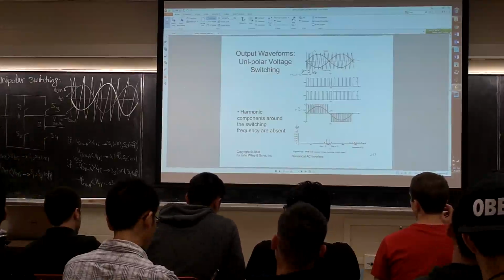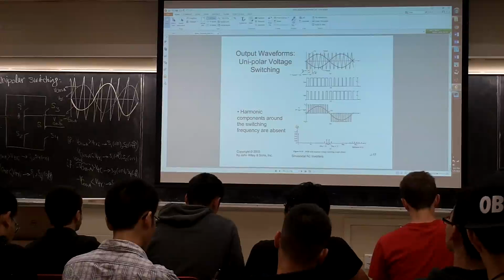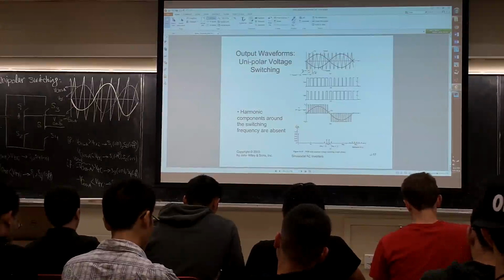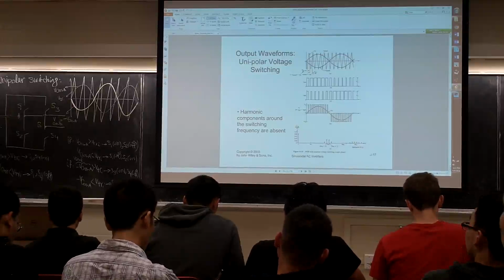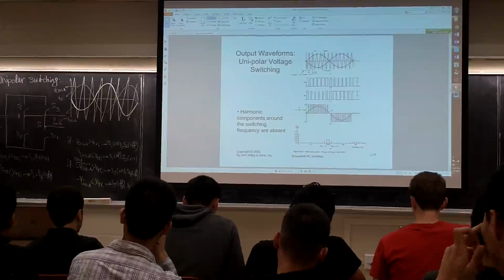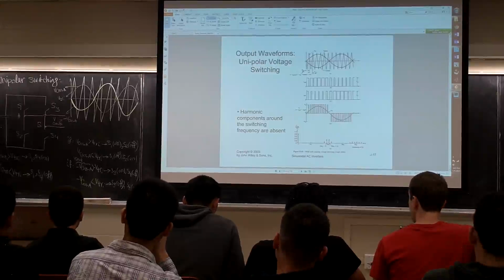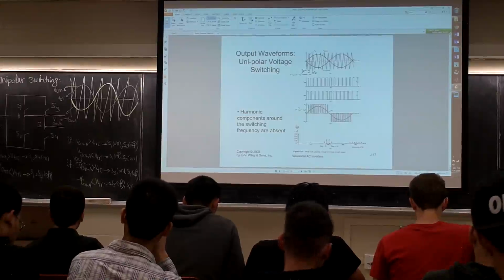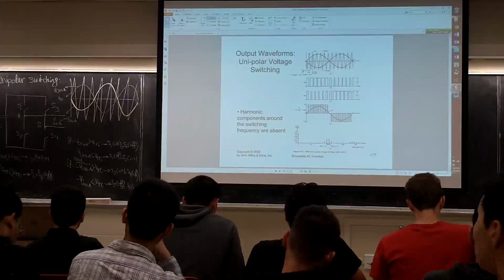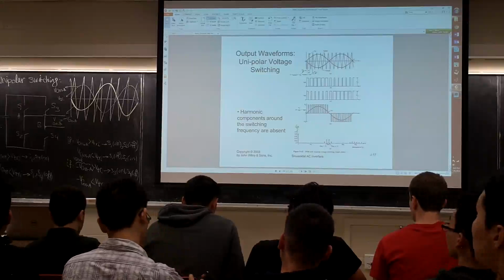This is the frequency of the harmonics at the output. It is going to be 2 J MF plus minus K times F1. J could be 1, 2, and so on, and what is K going to be? K has to be odd. K is odd. No, not odd.